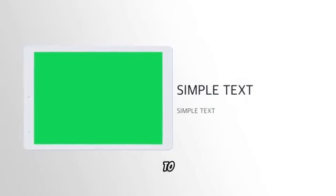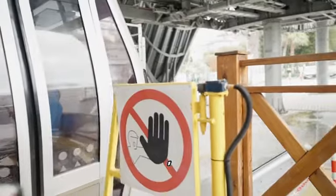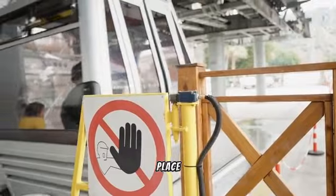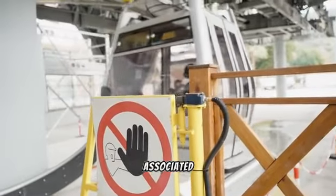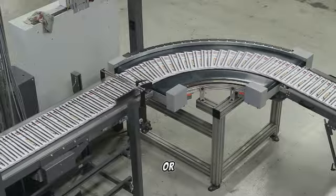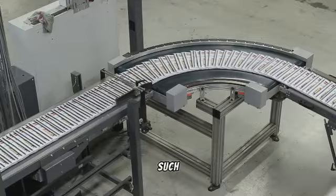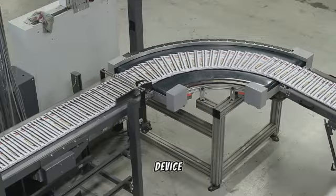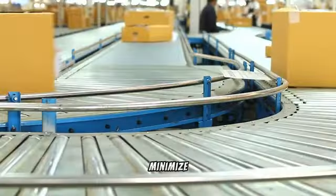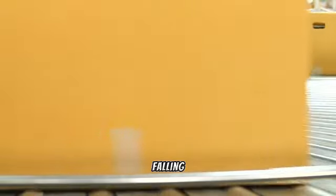The next step is to implement controls. So once you've identified the hazards, then you need to think about the controls that can be put in place to minimize the risk associated with the hazards. For example, for the hazard of material falling or slipping, we can put in place a control such as using a push or a pull device, or maybe a conveyor belt to feed the material into the machine. This will minimize the risk of the material falling or slipping.